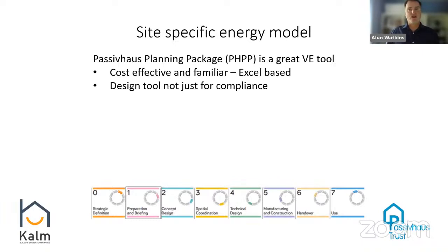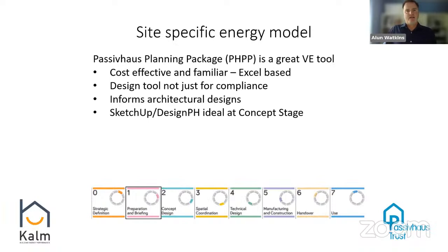It's a design tool. It's not just for compliance with the Passivhaus standard or with standards such as the AECB, which use the same kind of design tools. It is an overall design tool, so it can actually inform architectural designs from a very early stage. This stage is Design PH, which allows 3D designs in SketchUp to be very easily and quickly converted into PHPP, so you can see very quickly the effect of any design changes on the building energy performance.